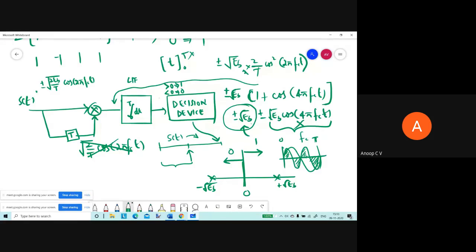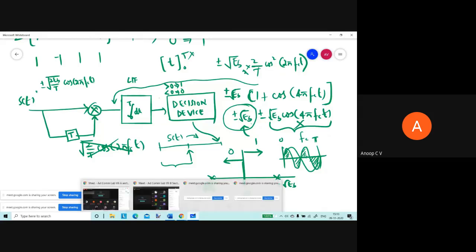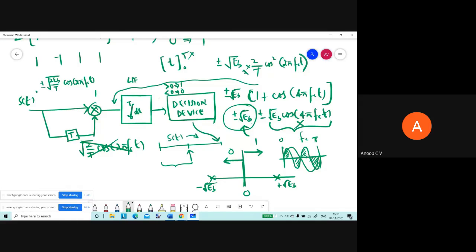So once again, I'll repeat. The first step is to multiply the signal of the current symbol with the previous symbol. It will be signals only. Then after that, we have to perform this integration. This is the second step. To perform this integration, we'll be using trapezoidal integration. For that, we have an inbuilt Matlab command, trapz.